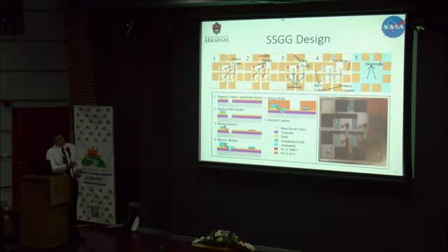This is a view of my lithography masks. So here you can see my heaters. There are my diodes. On this design, I've also included an independent test diode, so I can test the diode without the rest of the circuit. There's also a test heater here, so I can look at that. Step 3, again, insulator, contacts or bridges, and then microwells.